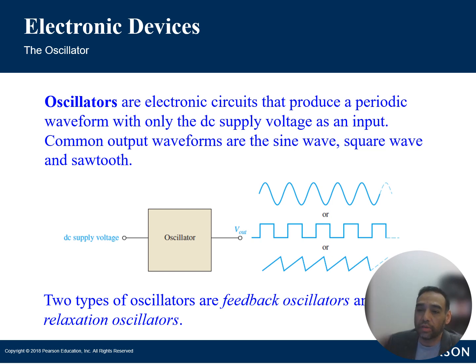So you have an oscillator circuit that includes mechanisms for regulating the output waveform's frequency and amplitude. Again, this can include feedback mechanisms to compensate for variations in those component values or some kind of environmental factor, depending on what the factors are for that device to be operated under. So overall, you're going to have a combination of feedback, amplification, frequency determining components, and phase shift components, which creates that self-sustaining oscillation within the circuit. And all of this is going to allow it to generate continuous waveforms at some specific frequency. Cool. Next slide.